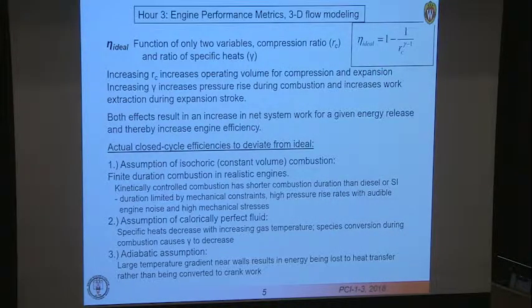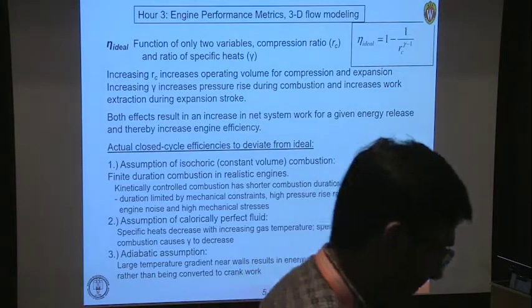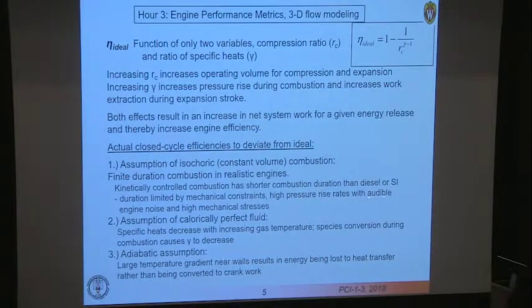But actual cycles differ from this. For example, the assumption of constant volume combustion is obviously not correct. Even with HCCI, very fast combustion, it's not necessarily isochoric or constant volume. We have a finite duration. The duration of combustion is also limited by mechanical constraints. Even if you could have instantaneous combustion, high pressure rise rates and audible engine noise, high mechanical stresses would make that engine undesirable.